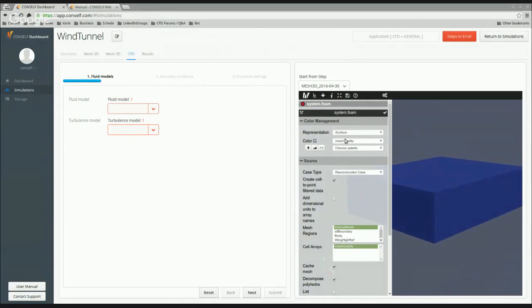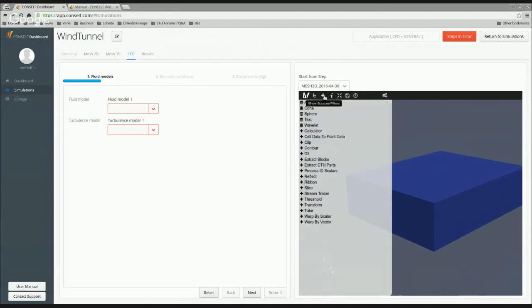The mesh quality is a cell-based value that is 0 when the mesh is good and 1 when the cell has problems. So one way to highlight where the mesh has problems is to isolate the cells with the mesh quality value equal to 1. In order to do so, you have to apply a filter called threshold.